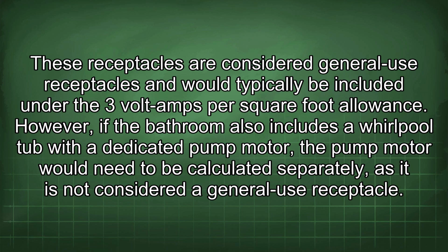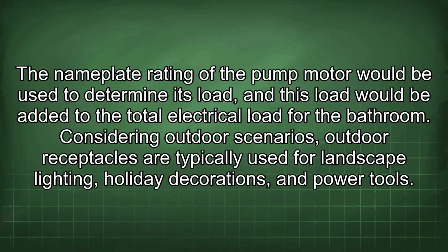However, if the bathroom also includes a whirlpool tub with a dedicated pump motor, the pump motor would need to be calculated separately as it is not considered a general use receptacle. The nameplate rating of the pump motor would be used to determine its load, and this load would be added to the total electrical load for the bathroom.